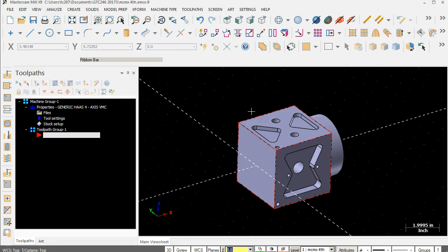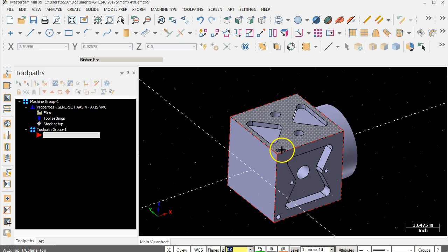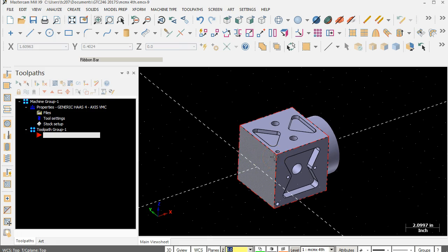But really, I just want to go through and see what each of the pockets, each of those values can generate. And then I put the holes in the corner because I want to see what a pattern will do. Do I need to create 4 separate operations to manage that, or will the pattern manage the rotations to each of those corner slots?